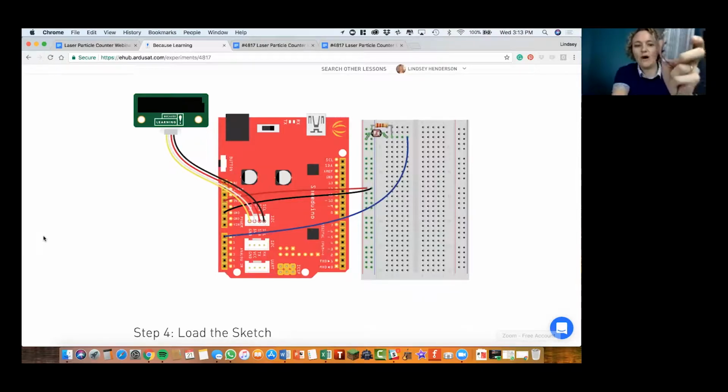All right, the blue wire. It needs to be in the same row as the resistors. Doesn't matter the position, really, just as long as it's in that same row as the resistors. And while I was building this with students, there's a lot of room for error with students plugging things into a breadboard. You could get one pin off just by one little connection and the whole circuit won't work.